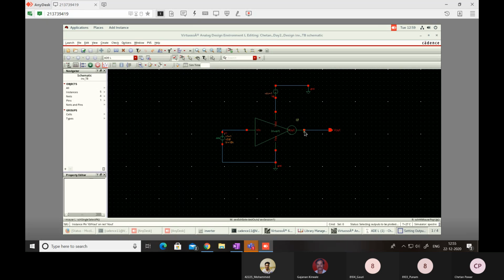And if you want to measure the current, you need to select these nodes, like the red color nodes that are there now. So here we want to measure the voltages, input and output voltages. So I will select this net. Net means wire. That blue color wire is a net. Okay. So I am selecting that wire. After selecting, now click that. Output wire, you click. Click on the output wire. Good. Only there. Now you click on the input wire. Okay. Selected.